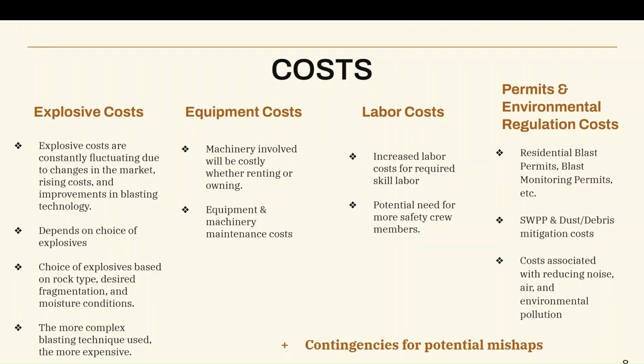Costs involved in blasting rock. The explosive costs are constantly fluctuating due to changes in the market, rising costs, and improvements in blasting technology. It's going to depend on the choice of explosives, whether you want to use ammonium nitrate fuel oil or dynamite. Depending on rock type, desired fragmentation, and moisture conditions, you will be able to make your decision on which type of explosive you would like to use. The more complex the blasting technique used, the more expensive.